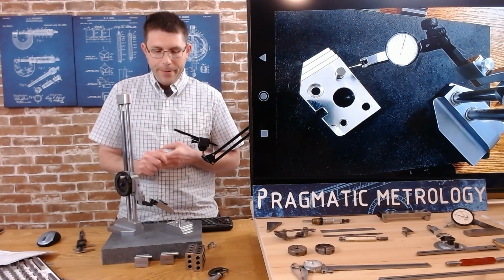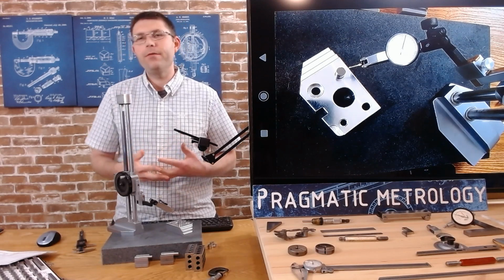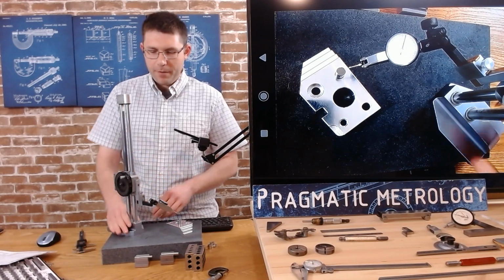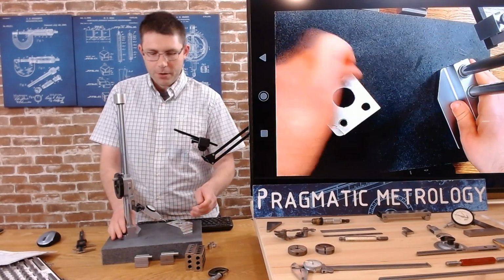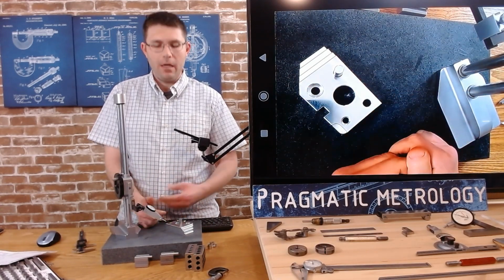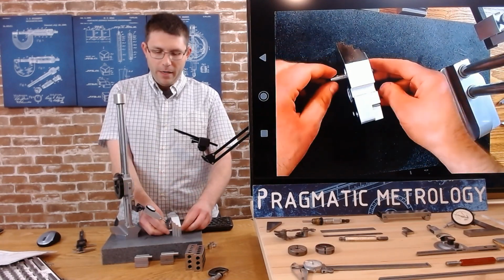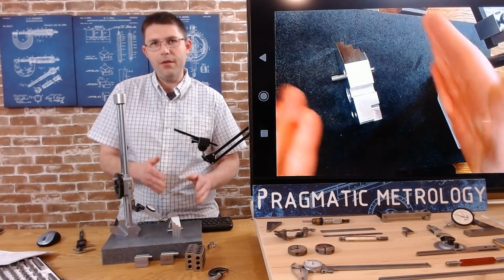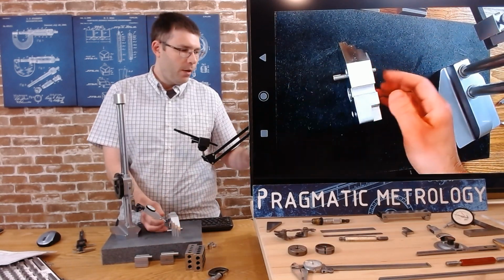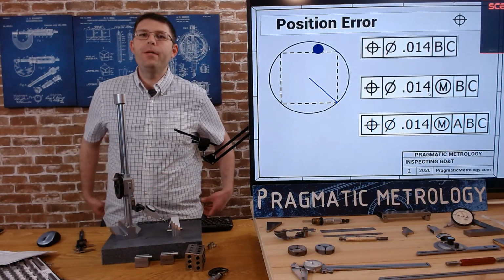So when you have tight tolerance, it's a little more important to do all this. When you have an open tolerance like 14 thousandths, which is not incredibly open, but if the part was manufactured in a repeatable manner, it should be okay to check it this way. However you want to check it is up to you. Just remember that this hole has to be in tolerance at every point, from top to bottom, from end to end. So those are a few ways you can double check that the three-dimensional position is correct.